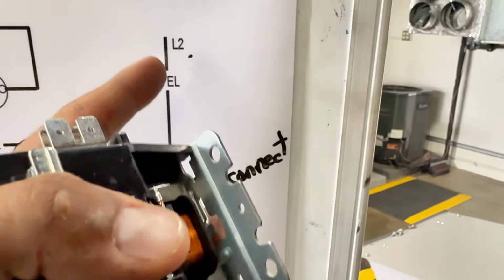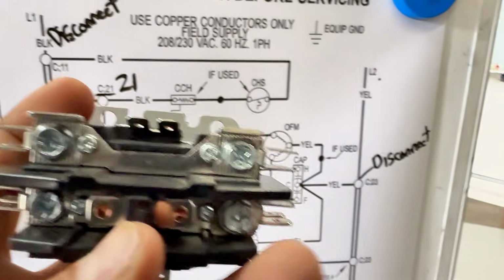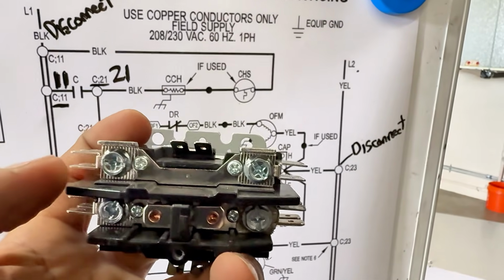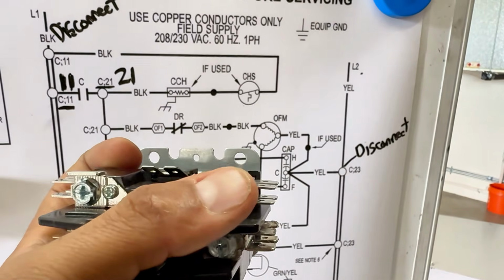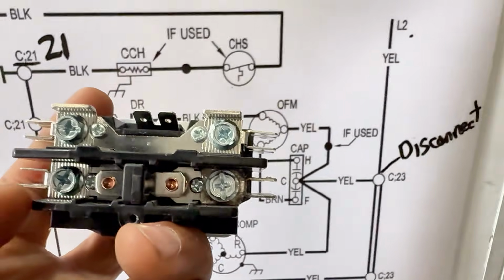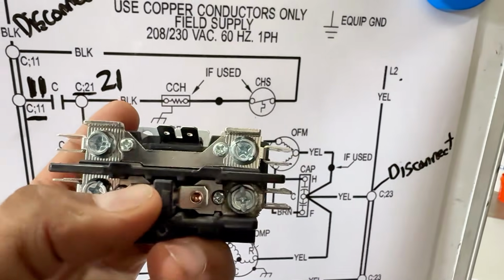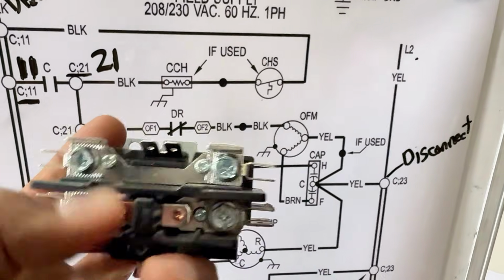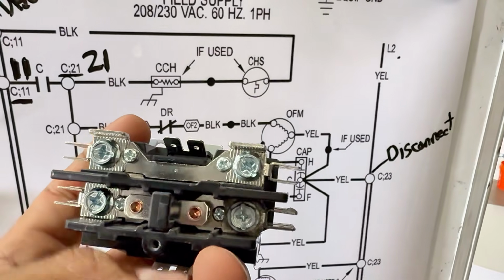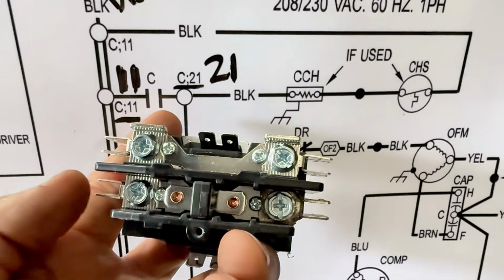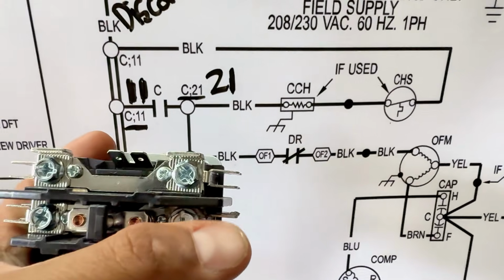And why is it that we just have 23, 23, 23? Because when you look at the contactor, there's nothing in between. It's just one lane. If I land power here, I'm gonna get power coming out over there because there's nothing in between. The reason on the bottom they put 11 and 21 is because you do have something separating it. You have a bridge that is controlled by 24 volts that you got to push in. That is why they put that one as 11 and 21 on the right side.